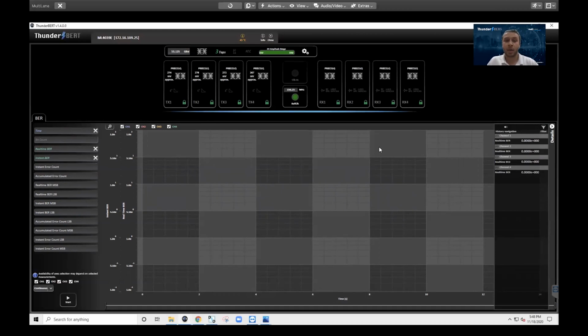And now we come back to the conversation of the equalizer. We come back to the conversation of optimizing signals for these DUTs. It's all about the trade-off between bit error rate performance on one side and power consumption on the other side. We have 400 gig electrical channels running error-free right now, but that's not very realistic of the type of electrical signal which is going to be fed into this DUT.